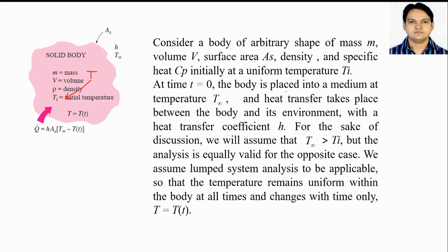At time t equal to 0, the body is placed into a medium at temperature T infinity and heat transfer takes place between the body and its environment with the heat transfer coefficient h. For the sake of discussion, we will assume that T infinity is greater than Ti. You can consider the example of an oven. You are cooking something in an oven, where T infinity is your oven temperature, which is high, and Ti is your food temperature. But the analysis is equally valid for the opposite case.